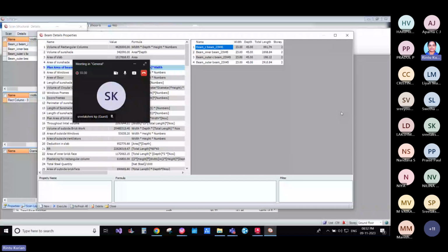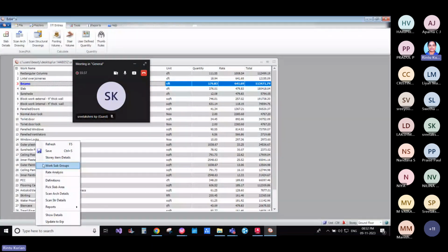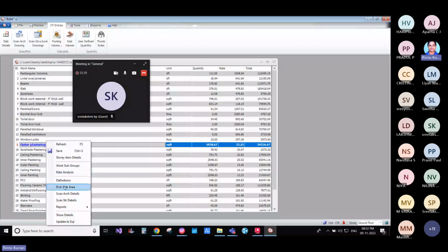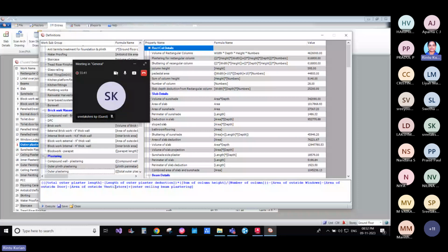These parts are later linked into the complete equation using the definitions over here. So whichever definition you are using, you can either take it directly from the property builder or create a combination of these small equations from the property builder to get the whole quantity. And why we are doing this is because sometimes we need data from slab to be deducted from the beam quantity. So these two are in two different tables. The data related to slab is in one table, data related to beam is in another table. We can't directly take the value from it.